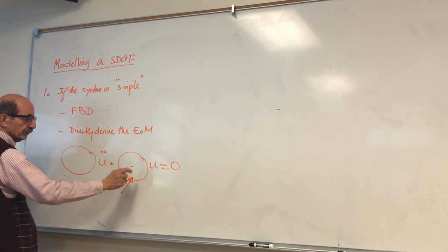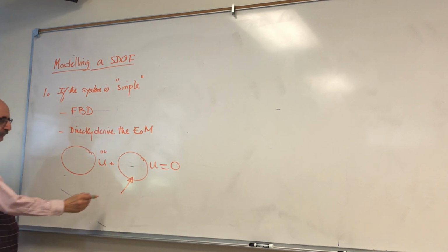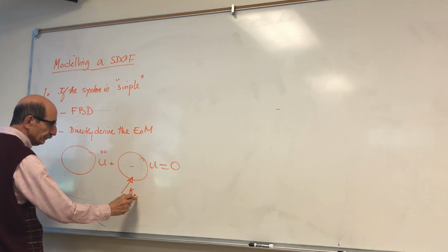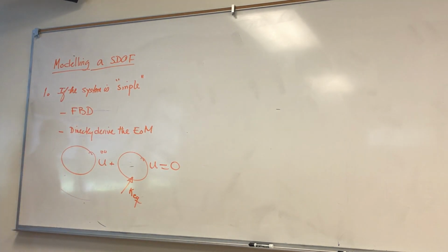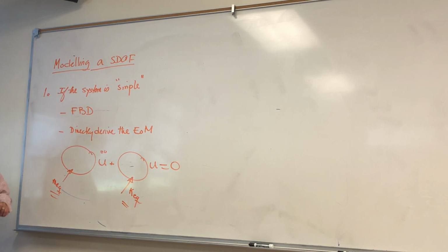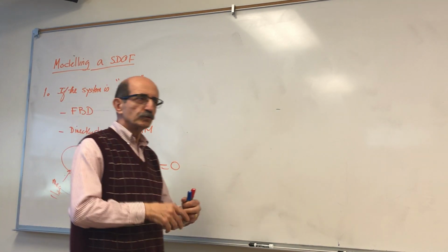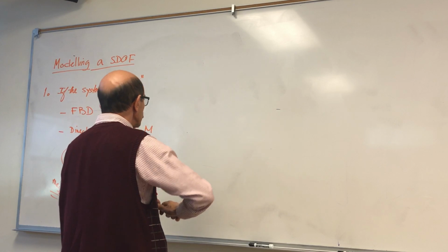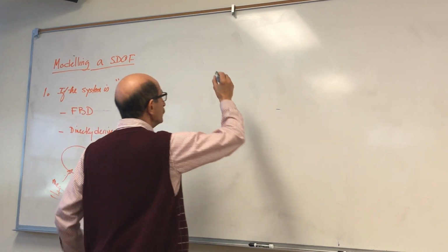Whatever is a component of the displacement term is the stiffness or the equivalent stiffness of the system. Whatever is a component of the acceleration term is the equivalent mass in the system. I did 1 or 2 problems last time. Let me do maybe 1 or 2 more before we get to the next level of complexity.